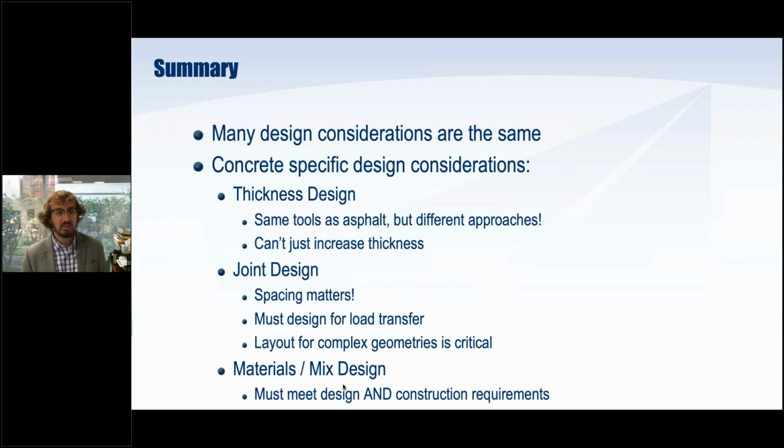So with that, just a quick summary of the things we're concerned with in concrete design. First thing is our thickness design. Understand that it's a lot of times the same tools as our asphalt design, but different approaches. Changing our thickness or changing the support underneath our pavement may not change the actual concrete pavement performance. So you really need to look at those other properties that we mentioned as we went through there.